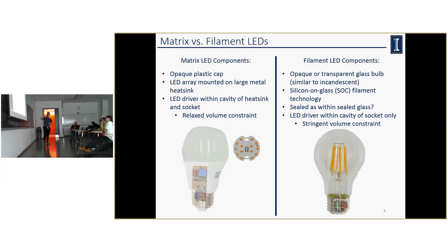And then here's the newer type, and as you can see, it looks very much like an incandescent, as I described. The reason it doesn't require such a big heatsink is that it has a much lower thermal impedance, so it can absorb heat much better. If you ever take apart one of these things yourself and turn it on and let it sit there, the bottom of it is made of metal and attached directly to that heatsink, and that heatsink gets really hot really quickly. Meanwhile, this thing, you can actually touch while it's on.